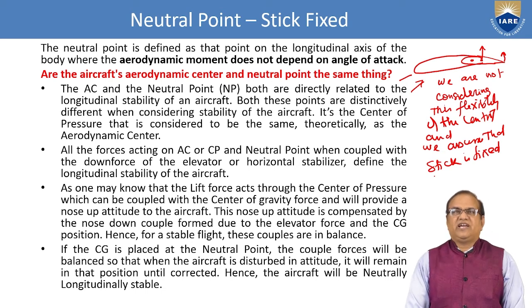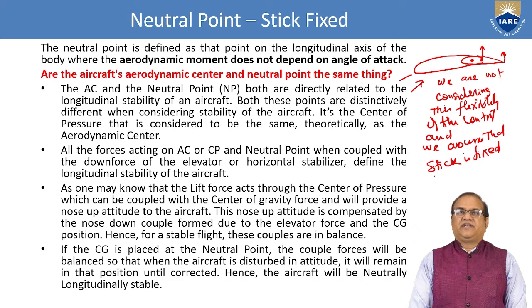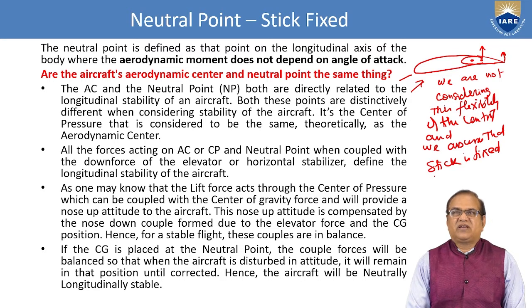So I am going to define first neutral point. The neutral point is defined as that point on the longitudinal axis of the body where the aerodynamic moment does not depend on angle of attack.